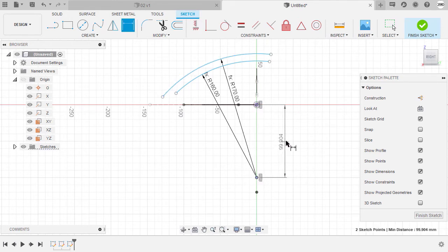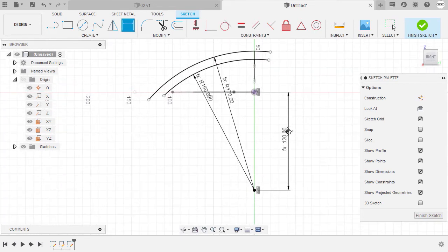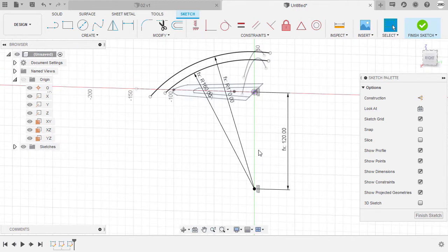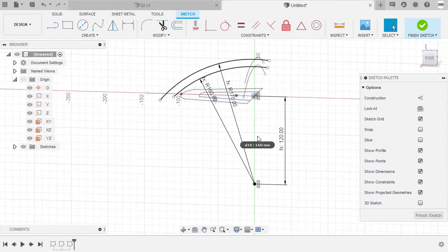And our center point, left-click here, and let's reuse those dimension IDs, D11, hitting enter. Hitting escape, or you may project the center point of these arcs and just add coincident. Once more, there are many ways to model this challenge.